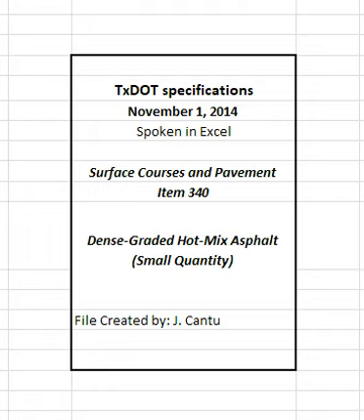Before drying to a constant weight, cores may be pre-dried using a CoreLok or similar vacuum device to remove excess moisture. The engineer will use the corresponding theoretical maximum specific gravity to determine the air void content of each core. The engineer will use the average air void content of the two cores to determine the in-place air voids at the selected location. The engineer will use the vacuum method to seal the core if required by Tex-207-F. The engineer will use the test results from the unsealed core if the sealed core yields a higher specific gravity than the unsealed core. After determining the in-place air void content, the engineer will return the cores and provide test results to the contractor.